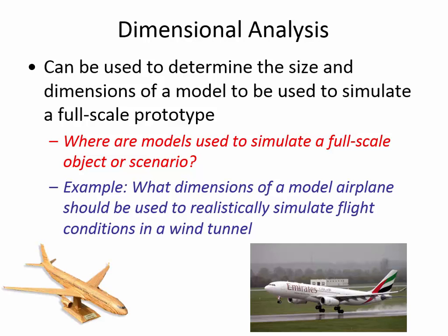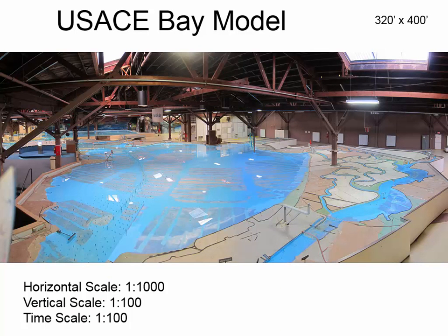tunnel. And so, a small-scale model can just be decorative, but can also be really useful in making subtle changes to the shape of an aircraft wing. You may have seen on a lot of planes nowadays winglets on the end of the wings to try and reduce fuel consumption. And those were developed in wind tunnels and with numerical experiments, computer simulations, and they knew what would happen before they bolted them on the end of actual wings. And so dimensional analysis helps a lot.